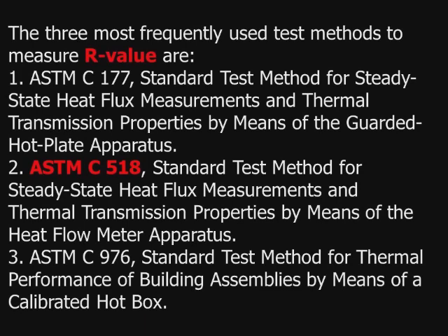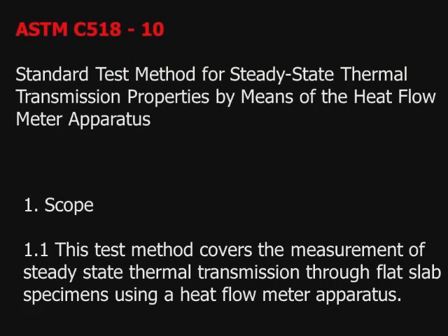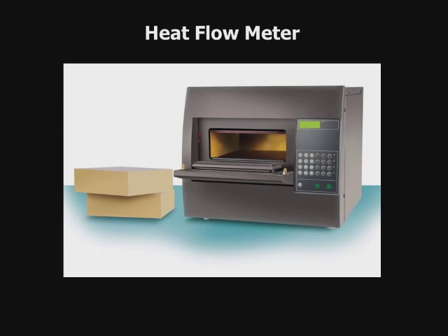So if you take a look at the most widely accepted test, ASTM C-518, the scope of this test is to measure how much heat, in units of measurement, is being transferred through a given material, and it's done in a heat flow meter apparatus.